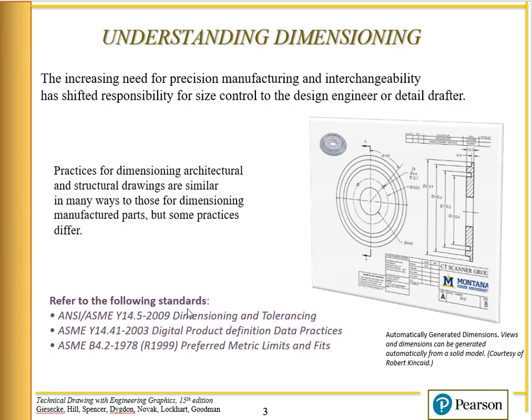Refer to the following drawing standards: ASME Y14.5 2000, that's dimensioning and tolerancing. Then there's also ASME Y14.41, that's digital product definition. And then ASME B4.2, these are standards for preferred metric limits and fits.